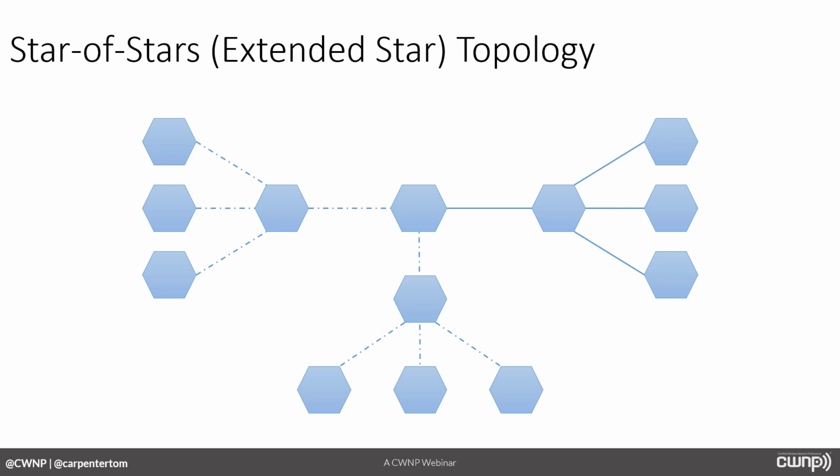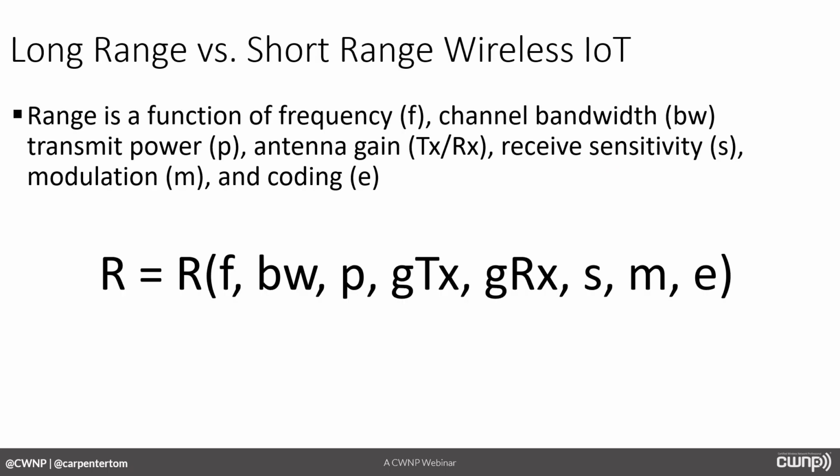So if I say LoRa, and I try to be scientific as best as I can in use of this terminology, if I say LoRa, I'm referring to that local link modulation protocol. If I say LoRaWAN, then I'm talking about the whole network that includes everything from the end devices through to the network servers that are involved in the whole process. Now, LoRa, the name, means long range. Simply LoRa, short for long range. So it's a long range protocol.